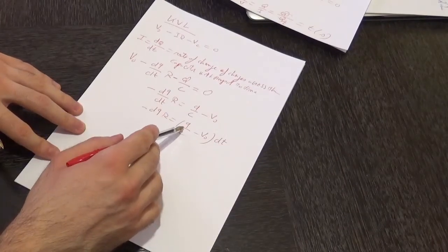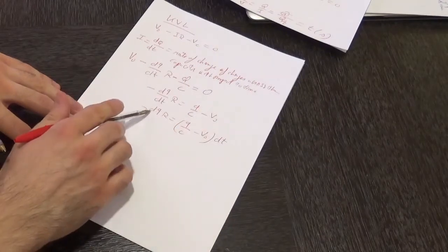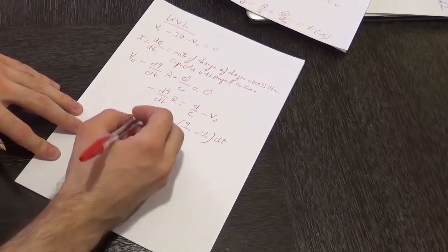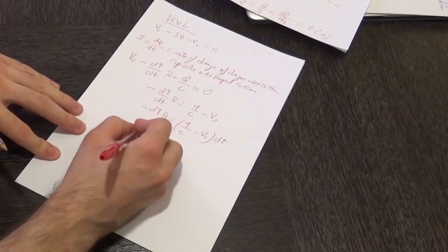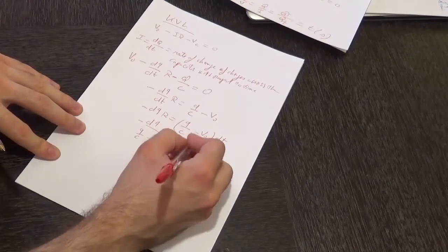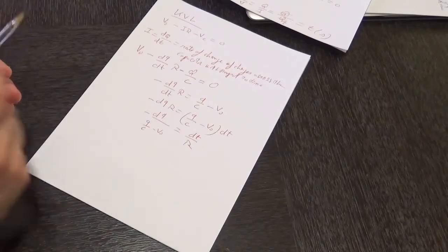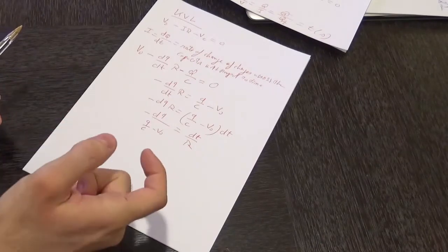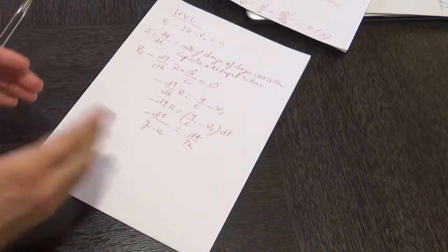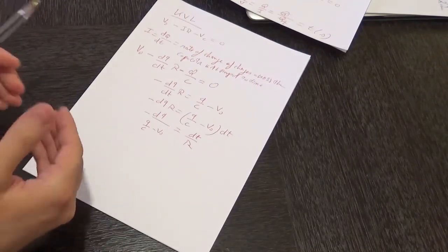Over here we have that Q variable, which is on the other side, so we have to bring it to the same side of the dq variable, and then we take R to the other side. So we have minus dq over (Q over C minus V0) equal to dt over R. Now after reaching that equation, we have to alter that expression in order to feature a term which corresponds to the time constant, because the time constant is going to be crucial in any equation in order to determine later on the voltages or the currents or the amount of charges.